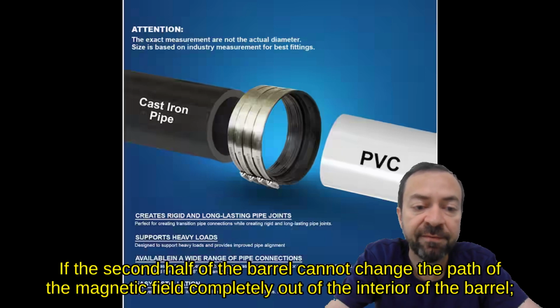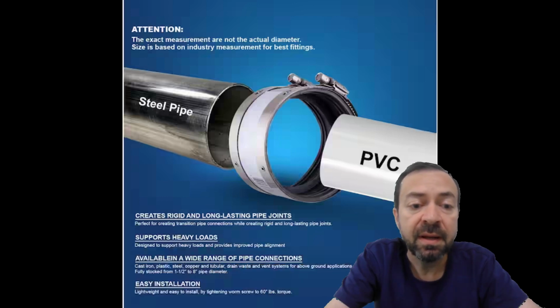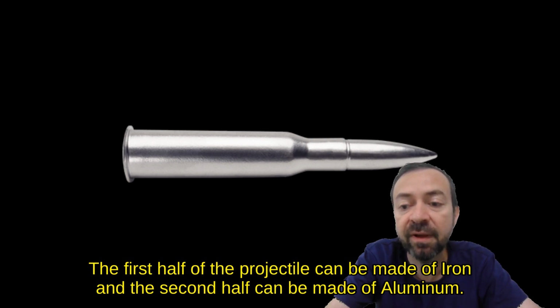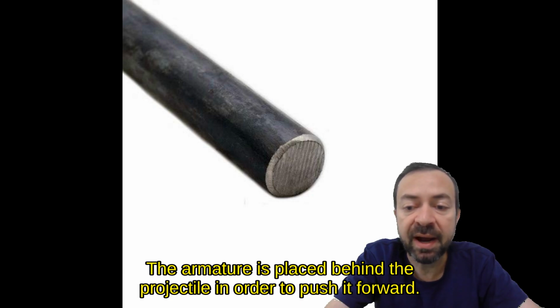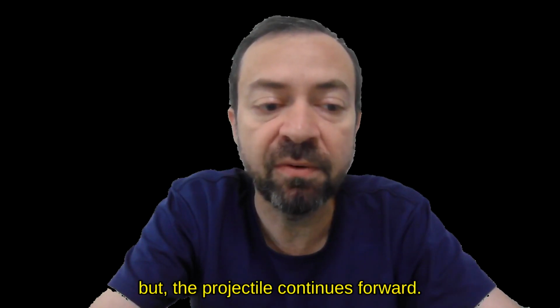If the second half of the barrel cannot change the path of the magnetic field completely out of the interior of the barrel, then the same solution can be applied to the projectile. The first half of the projectile can be made of iron and the second half can be made of aluminum. The first half of the projectile is called the armature. The armature is placed behind the projectile in order to push it forward. At the middle of the coil, the armature is pushed back, but the projectile continues forward.